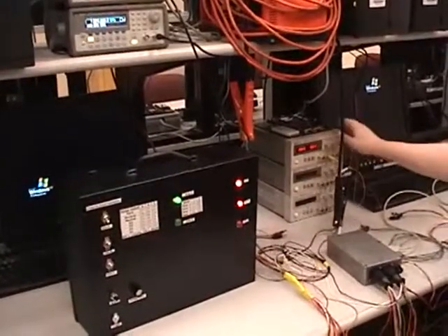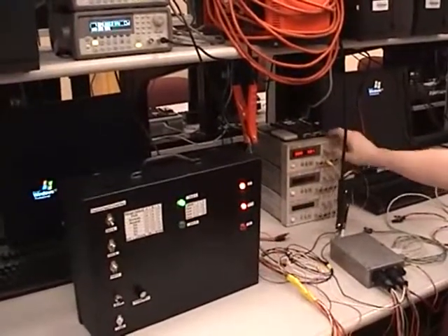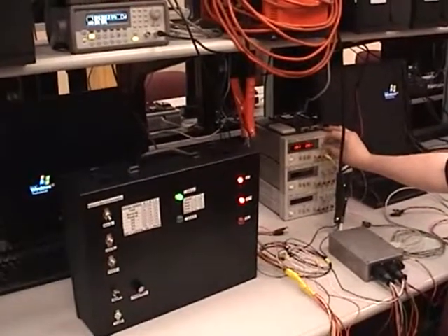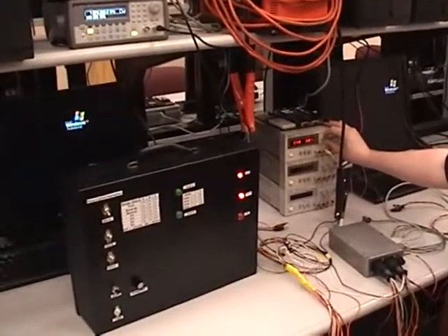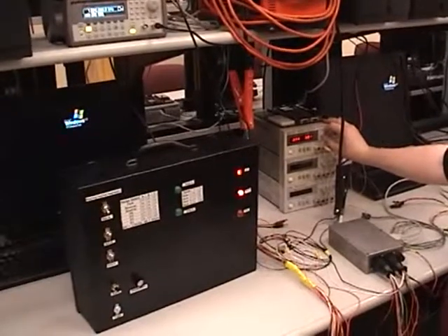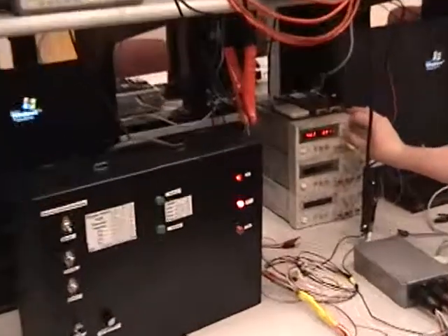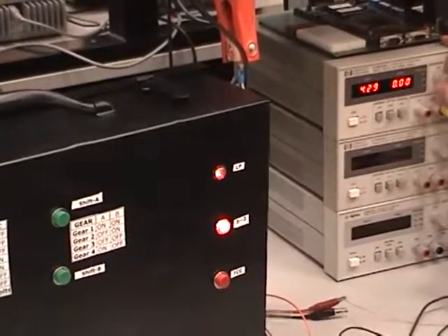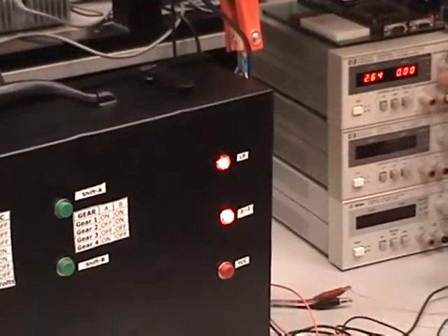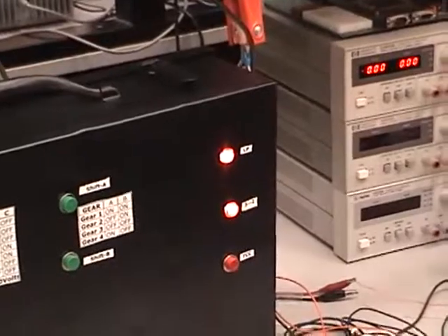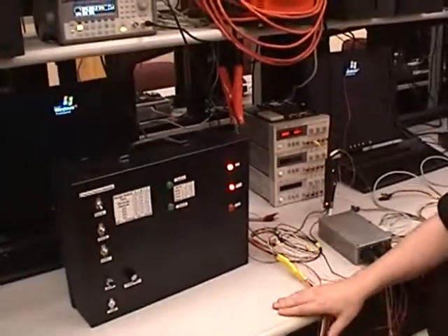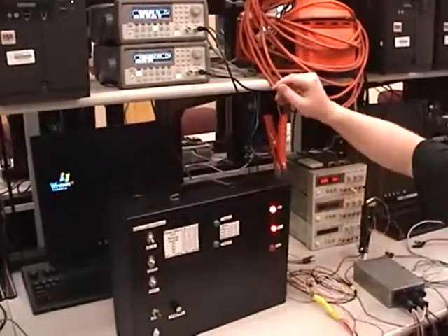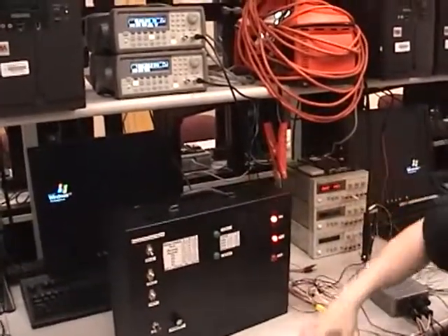This car obviously wouldn't be going this fast if you had zero throttle, but if we started easing the throttle down, you'd see that it jumps down to third gear, and then if we floor the car, we're not able to get it to shift all the way to second, but if you had your shift chart configured for performance driving or strip driving, you would see that it would occur.